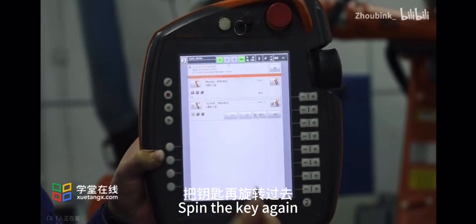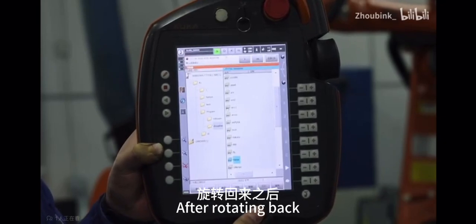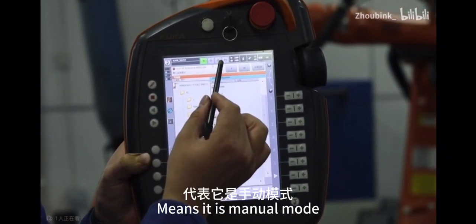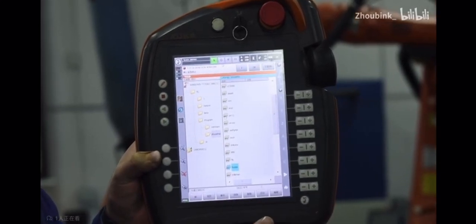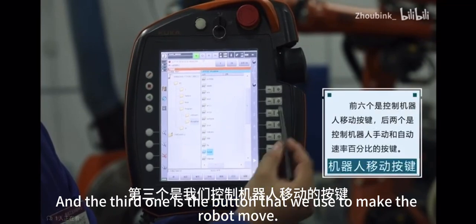Spin the key again. Click TE and rotate the key back. After rotating back, the first line of the status bar will display TE, which means it is manual mode. And the third one is the button that we use to make the robot move.